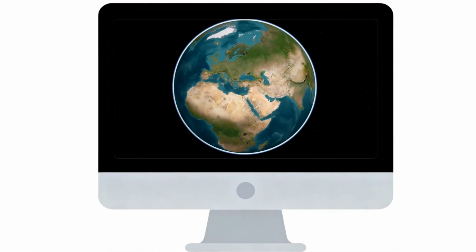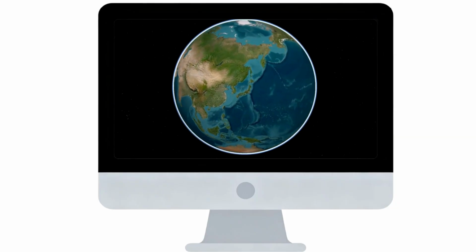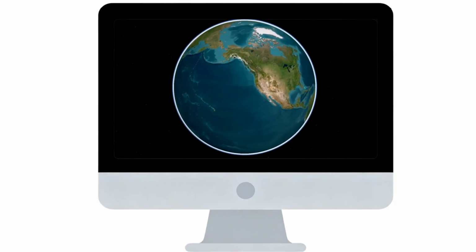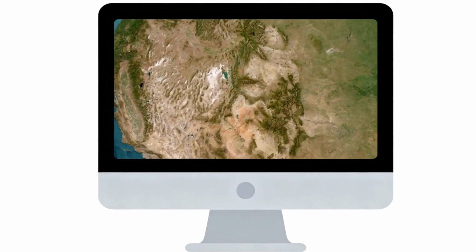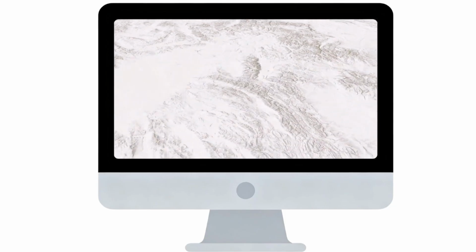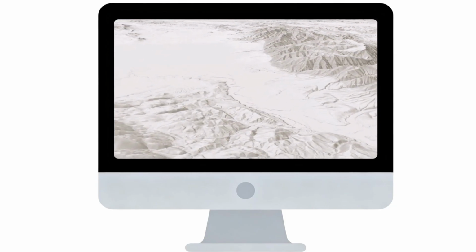Yeah. But GIS software mostly operates on a 2D monitor. Right. The real world is 3D. Our screens are 2D. We have to flatten the Earth, which means we have to break the math. Yes. Going from a 3D geocentric model to a 2D plane requires a map projection. And it is physically impossible to flatten a sphere without introducing mathematical distortion.